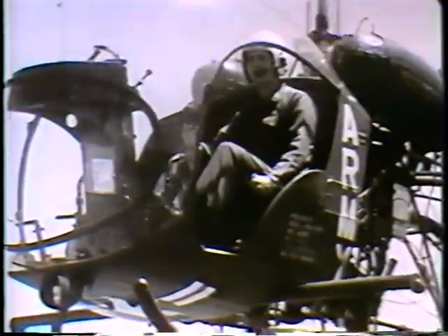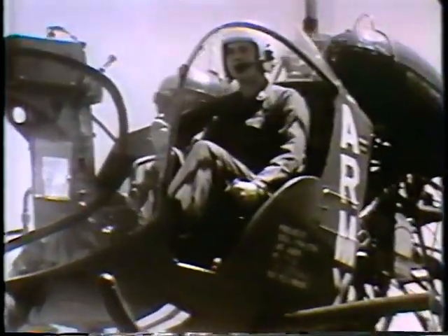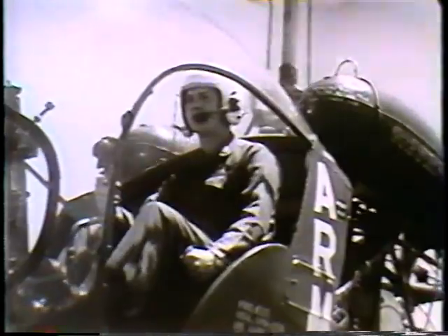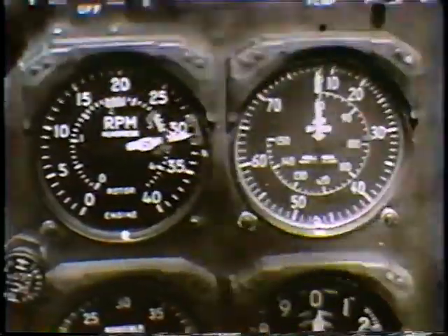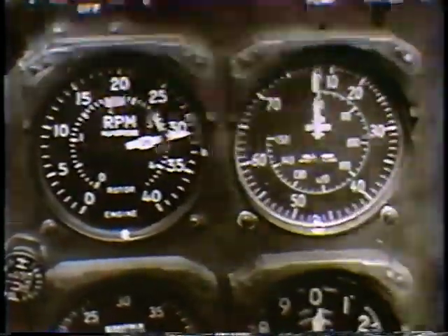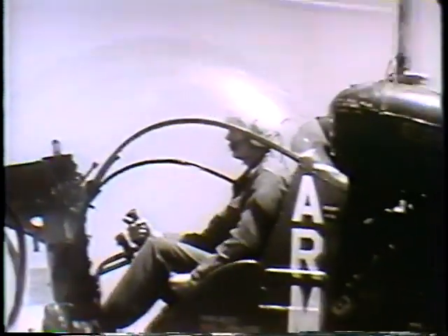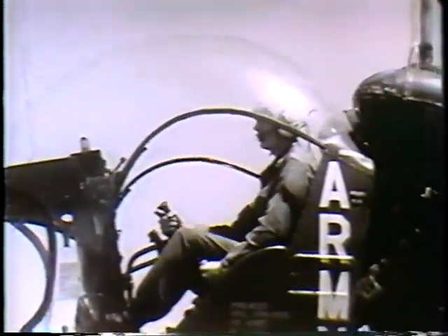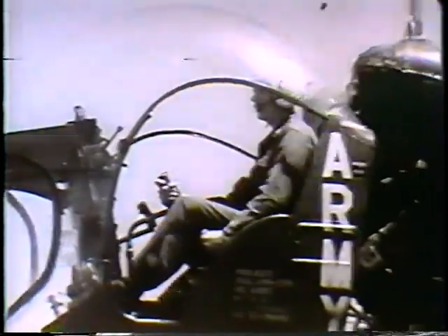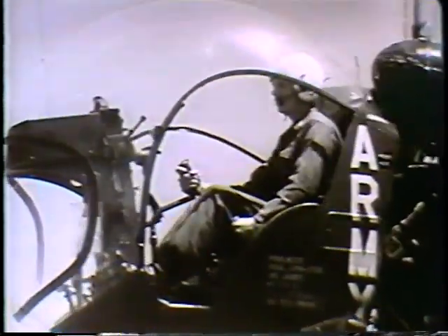Whether a helicopter is in flight or at a hover, the pilot maintains a constant rotor RPM. Therefore, the way he varies lift is to vary angle of attack. To understand lift fully, however, you must understand not only angle of attack, but also angle of incidence, which is sometimes called pitch angle.